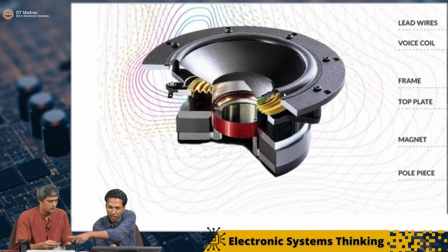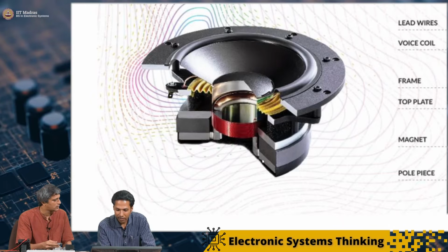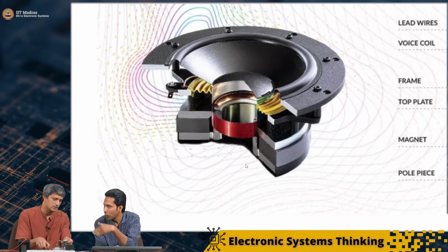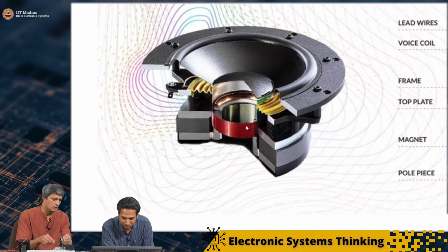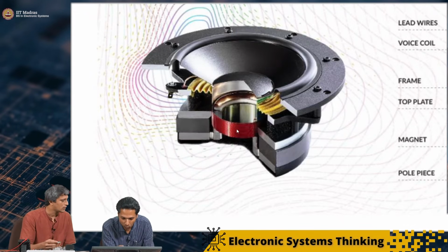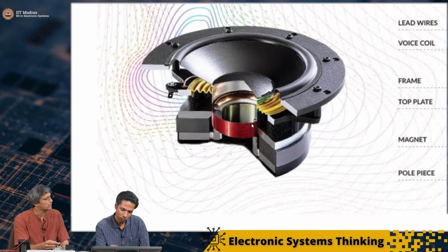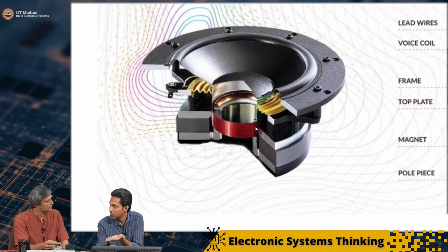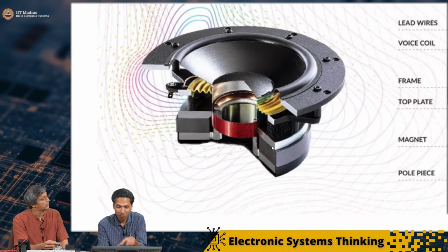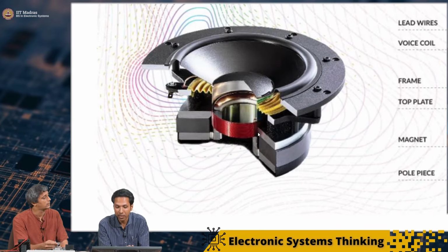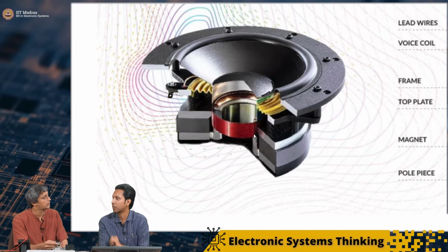That's the one at the top, and then the current that we are sending through these two wires is flowing through something that is visible here. You see a coil. This coil is able to move up or down. How? Because you are sending the current through the coil, and the coil is present in a constant magnetic field.